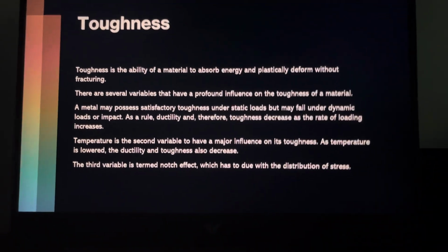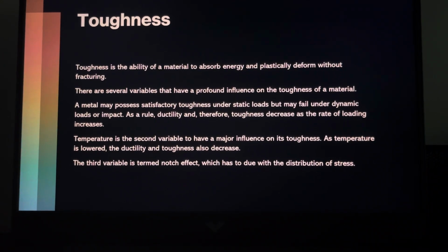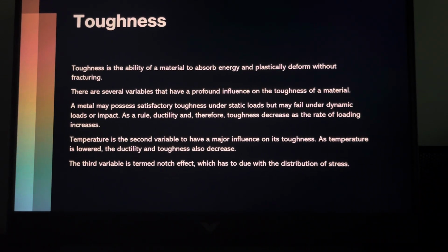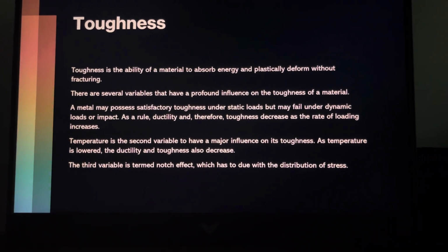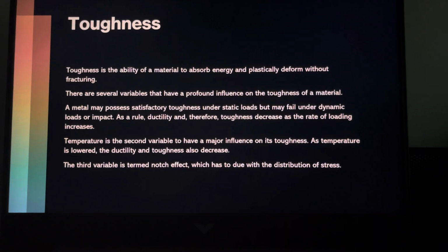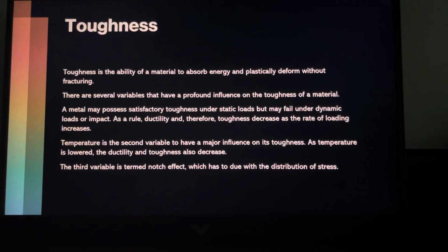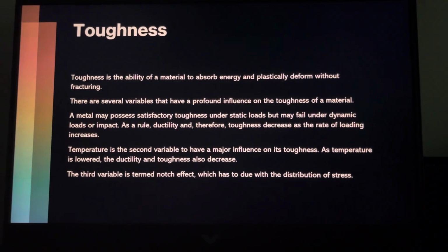Toughness is the ability of a material to absorb energy and plastically deform without fracturing. So one definition of material toughness is the amount of energy per unit volume that a material can absorb before rupturing. It is also defined as a material's resistance to fracture when stressed.